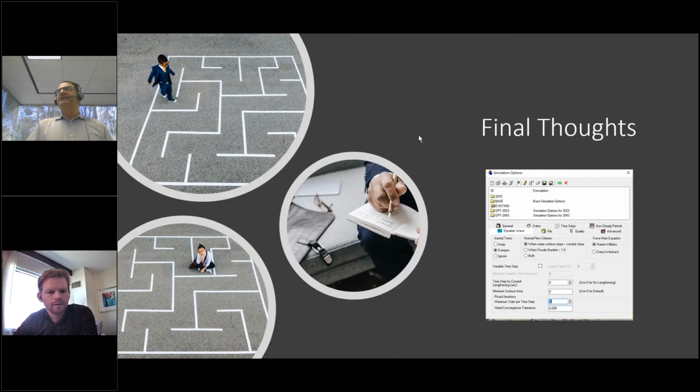And just final thoughts in terms of the continuity error. If one of my team comes and says, okay, we have this model, it's done, I ask, have you checked the continuity error? How does it look? I like to definitely see something below 5%, and oftentimes we're able to achieve below 1%. What you can do is control your time step, reduce your time step to allow the solution to converge. And that's basically what you can do with the SWMM engine.